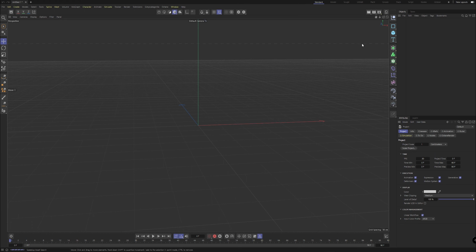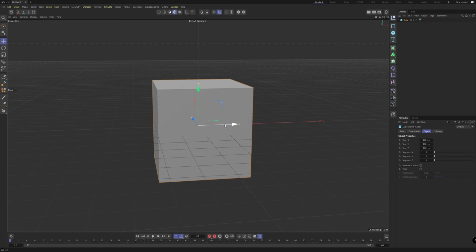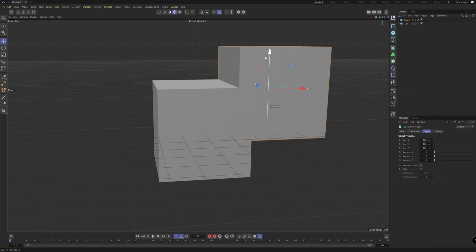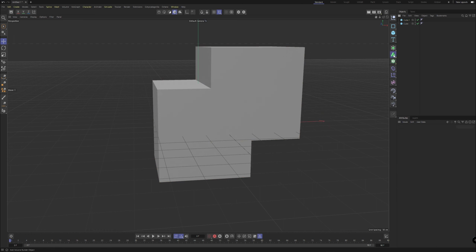My thought process, or generally the way you work with Volume Builder, is that you work by having a variety of shapes and geometries. Most of them we'll probably get from here, but we can also model some ourselves. Some are going to be adding to the voxel shapes, which will eventually be baked, and some are subtracting. So the way you have to think about that is, I'd rather show you: if you have a cube, it's a super crash course, then you have a second one, which is a little bit higher like this, and you put them both into a Volume Builder, remembering that Cube 1 is the second one that you've duplicated.